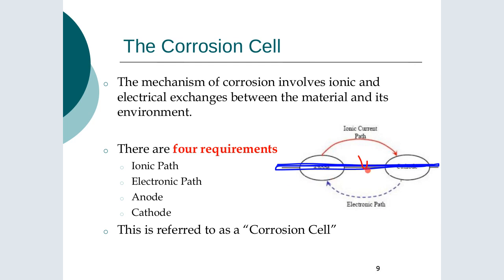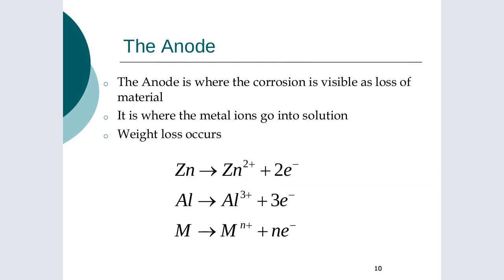If you have damage and corrosion starts to occur, a little thin layer will open up, of whatever, 100 microns, small gaps, and inside there you have different mobility of ions, and you get a localized change in the environment and a very accelerated aggressive attack, again way faster than what you expect. And this may be occurring underneath the paint surface. So you've got damage somewhere, it's in the seat, and then it's progressing and eating away material. But when you look from the outside, it seems perfectly fine. Corrosion can be quite an insidious thing.